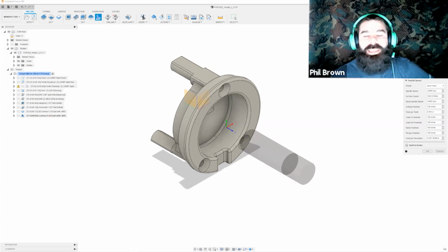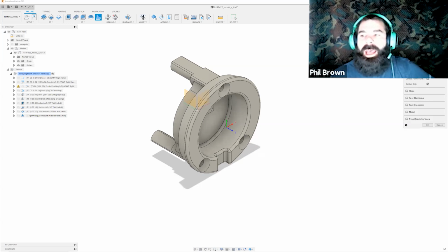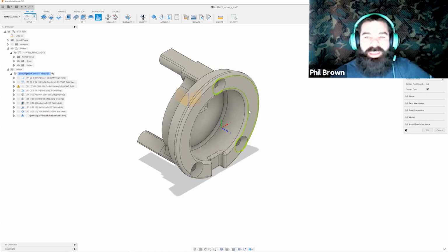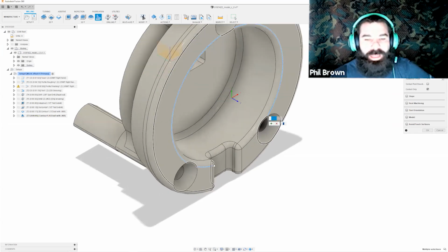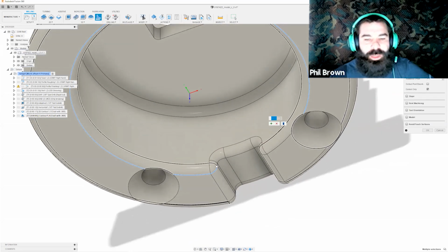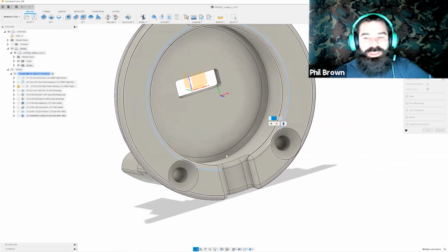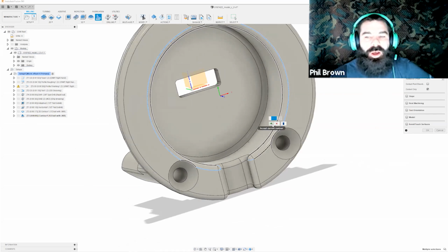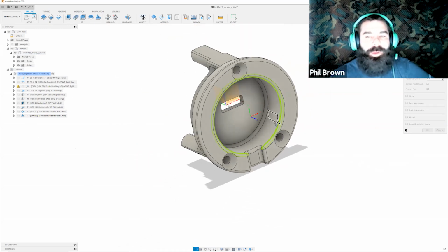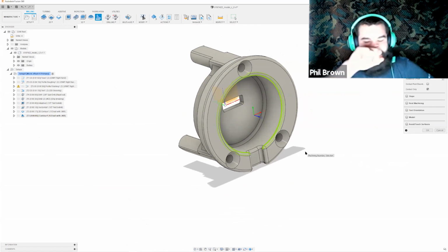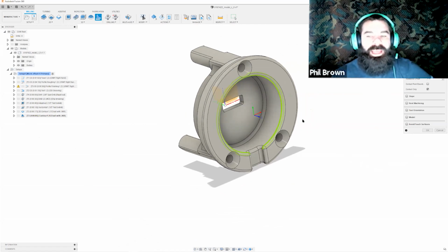So you do get things like the 3D adaptive clearing, 3D toolpaths all in one. I'm going to go ahead and say, let's do a selected boundary this time. And that boundary I want is chosen right off of my model directly. This is one thing that used to drive me absolutely crazy when programming in other software, is the ability to create a geometry chain on my actual geometry. I don't want to project stuff into a sketch and circle back and forth to keep going with this. I could simply pick that right there to go around.